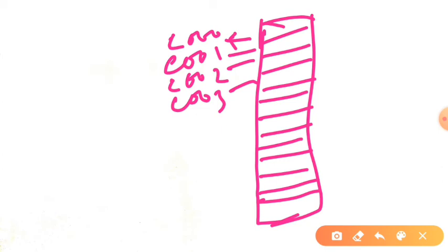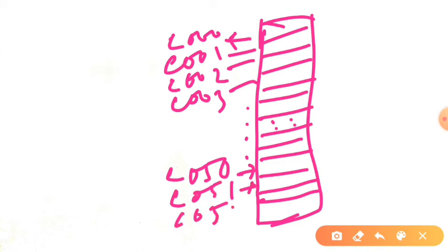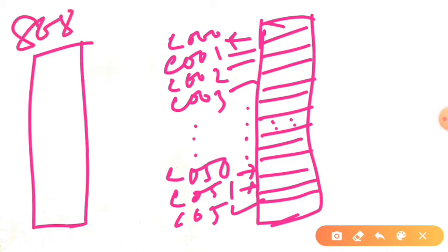Now let us understand. This is a memory location, C050 maybe, and suppose here we have dots. So this is C050, then next is C051, then C052. Obviously this memory address will progress in this way. Now when the 8085 microprocessor IC fetches instructions from memory, it needs the starting memory address, and then it fetches all the instructions written in the subsequent memory locations.